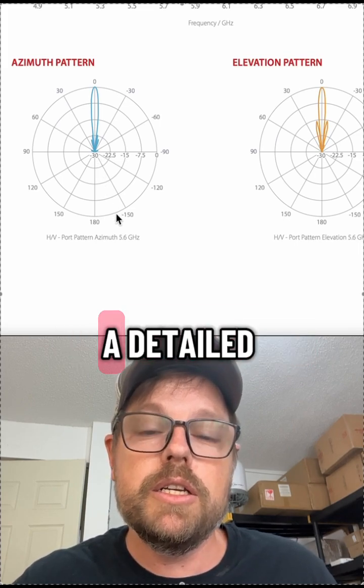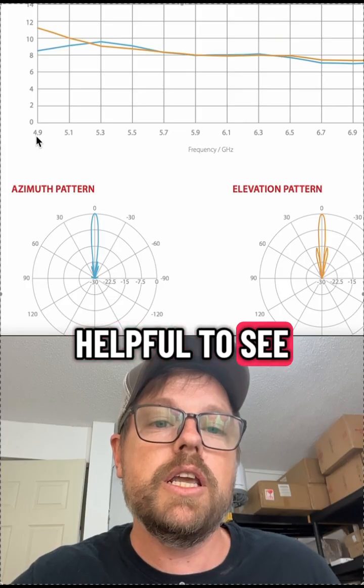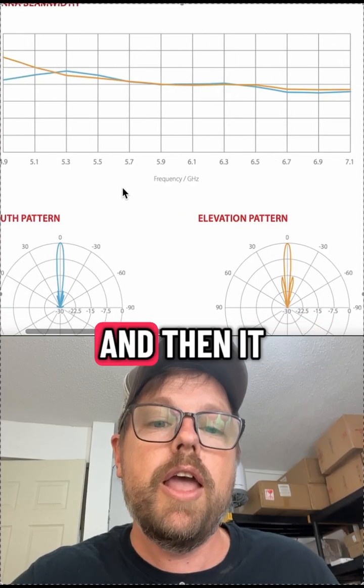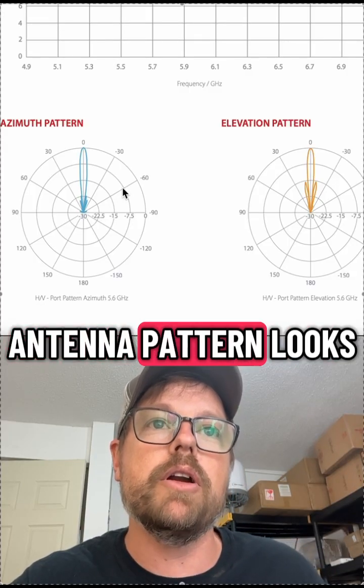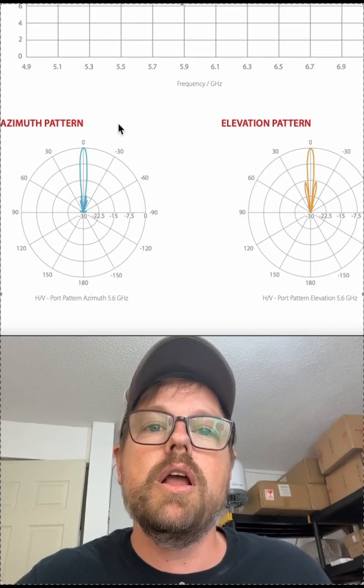You want to see a detailed antenna pattern, and it is helpful to see an antenna pattern at the beginning of the frequency range, at the end of the frequency range, and then it is helpful to have the ETSI mask to let you know how that antenna pattern looks relative to industry standards.